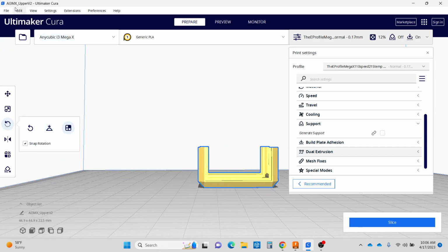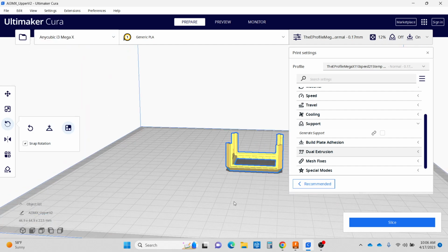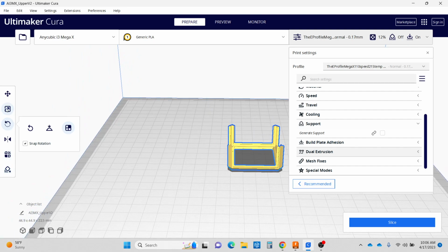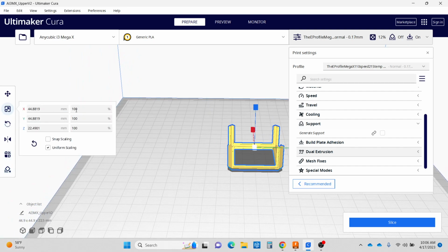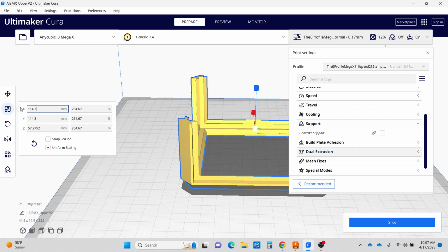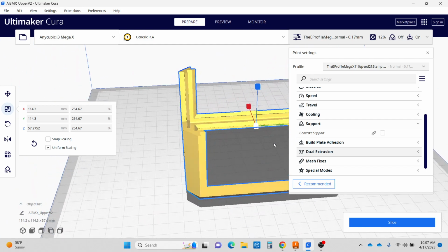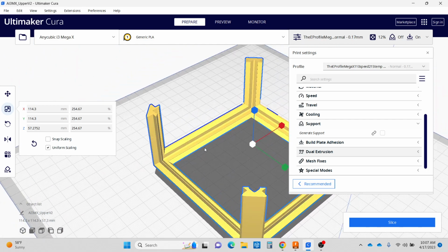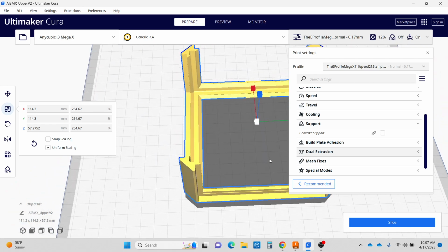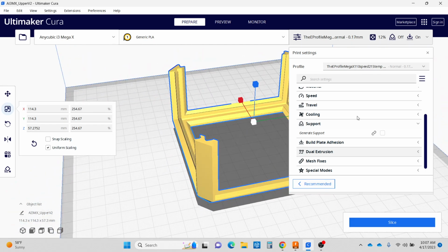Now I can lay it flat. After that, I can go to arrange all models. So that is in the center of the build plate. Crazy thing is we know that is not the size. So the scale is 114.3. That's 4.5 on X across the front. So when you do that, notice that it went ahead and calculated and gave us everything that we need. So that's the number that you're going to get. And then we can hit okie dokie. So we can slice this booger up.